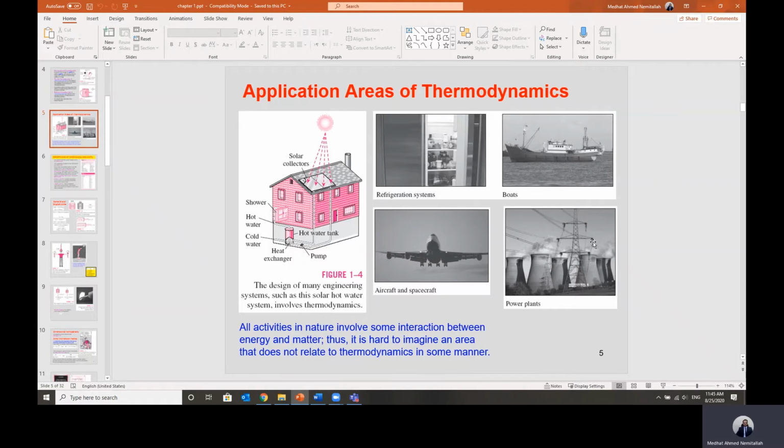Like the aircraft, we also burn the fuel to have a thrust force to move this heat engine. And in an electrical steam power plant, we burn the fuel to boil water and convert it to steam. Then we can expand this steam inside the turbine. Then we can generate shaft power, which can be connected to an electric generator. Then we can generate electrical power.